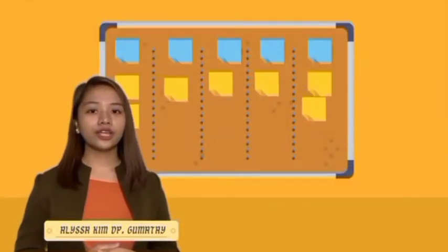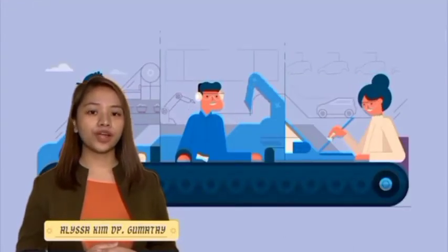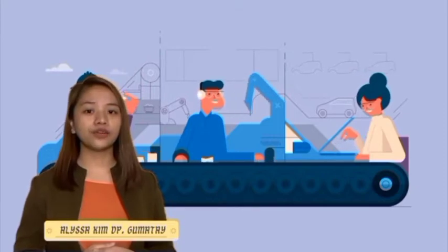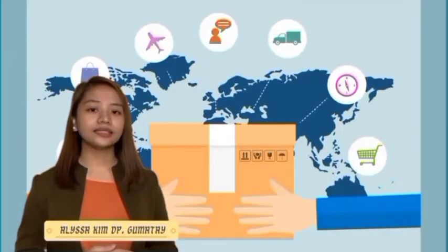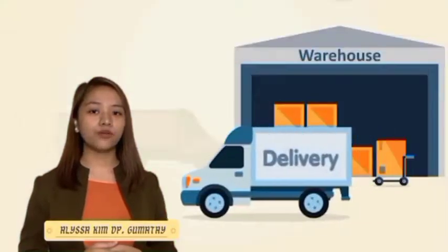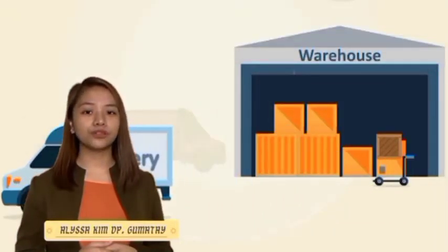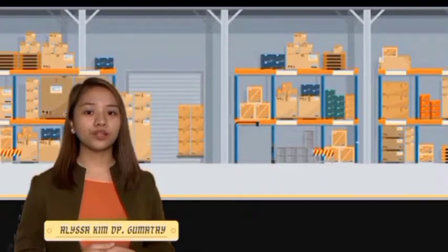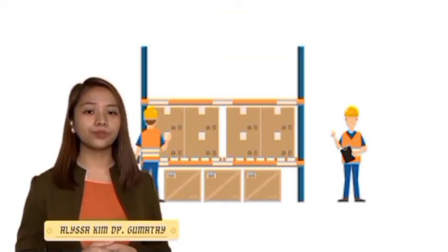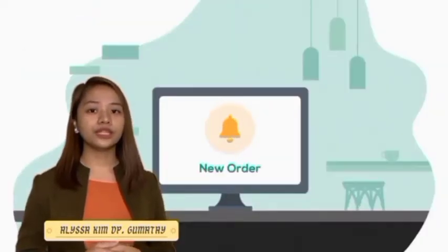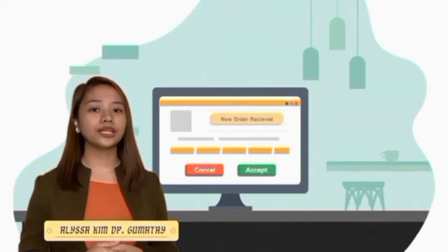A card containing all information required for the job to be carried out on a product at each stage of its journey to completion is what the Kanban system actually is. The essence of this concept is that the supplier will only deliver the components to the production line as and when they are needed, so that there is no storage in the production area. Moreover, these cards are used to control the work in progress, production, and inventories, and enable the business to adopt the just-in-time production and ordering system.